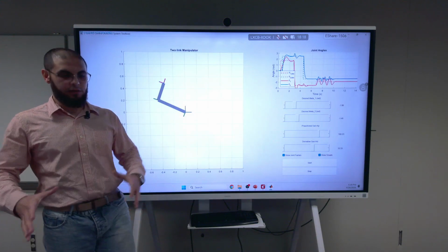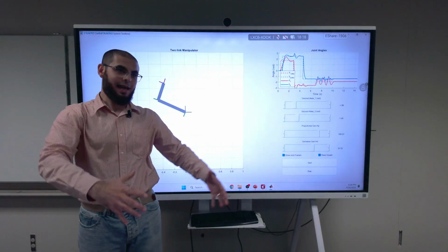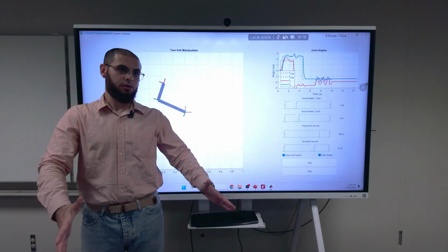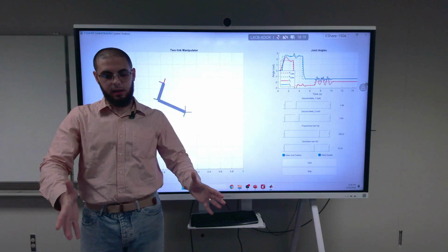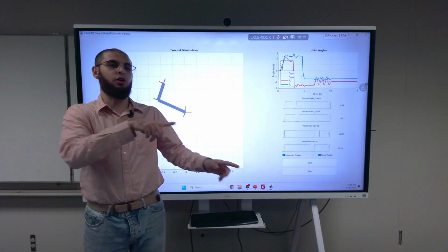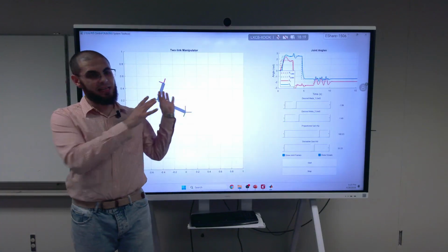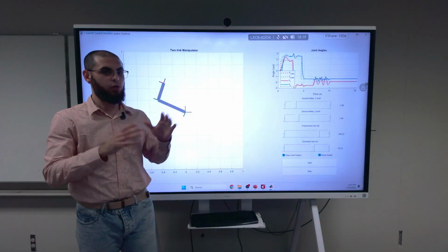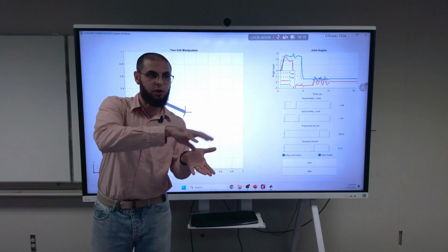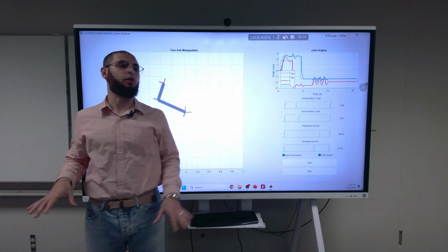Forget about the wheels. If you have a mobile base, think of the whole base on the ground as just one rigid body attached to the ground with a planar joint. So it's allowed to move everywhere. And in the end, for the forces that you want to move with, you can do a control allocation to say, okay, I want this wheel to move with this speed and this wheel to move with that speed, or this torque and so on. You can usually do it the other way around. Exactly what we did with the drone application last time. We designed a controller for a wrench on the whole rigid body, and then we transform the wrench. We say, this is the desired wrench I want. What are the actuator inputs that will give me that wrench? We separate the problem.